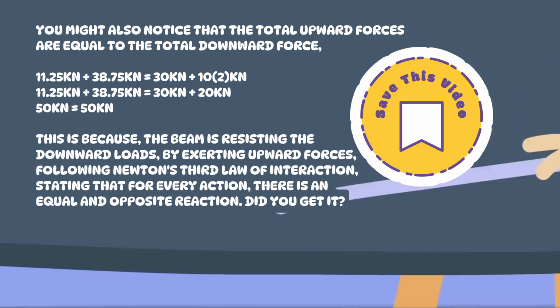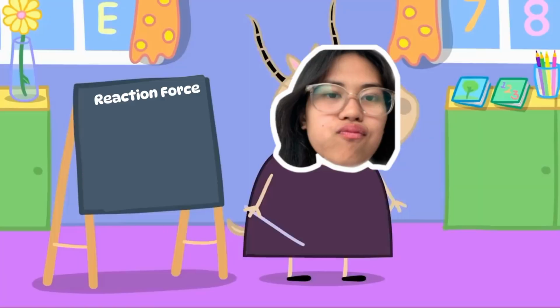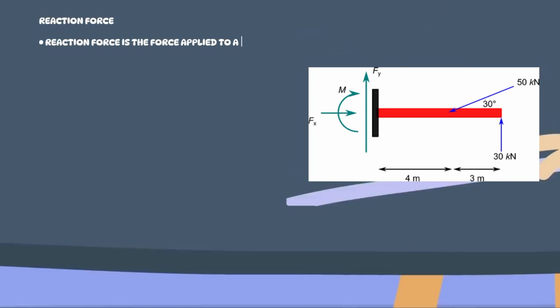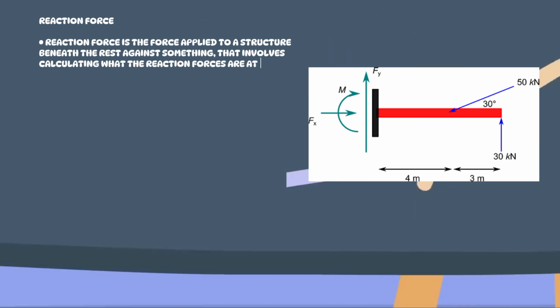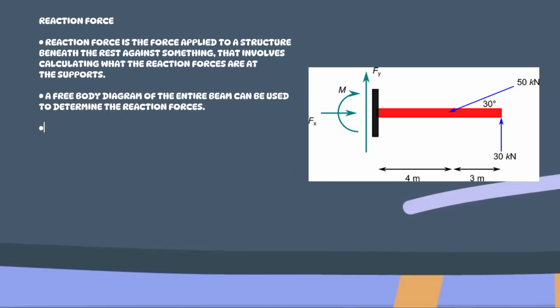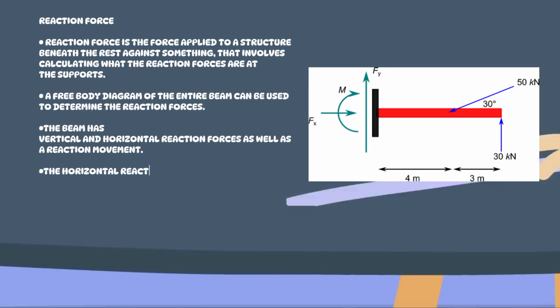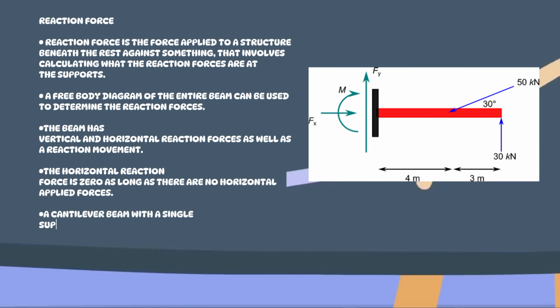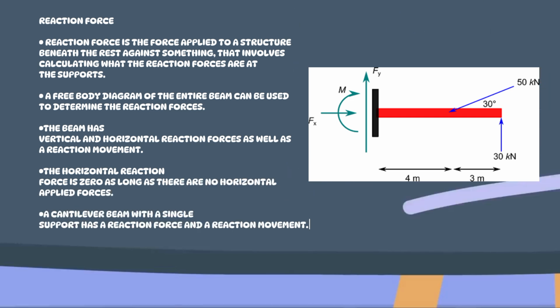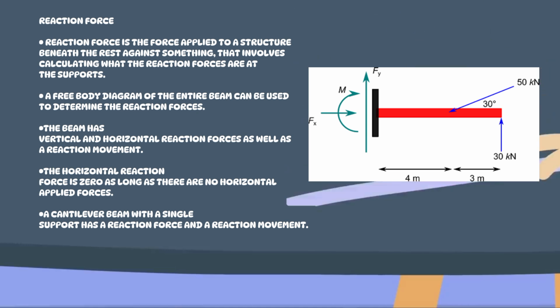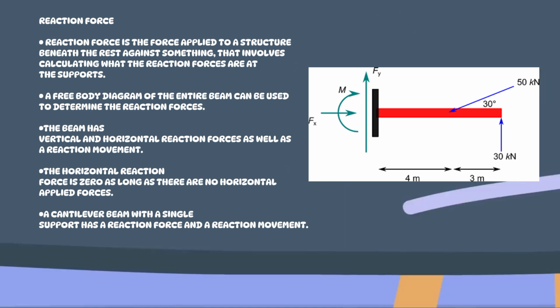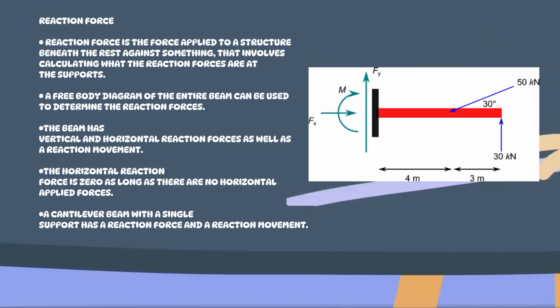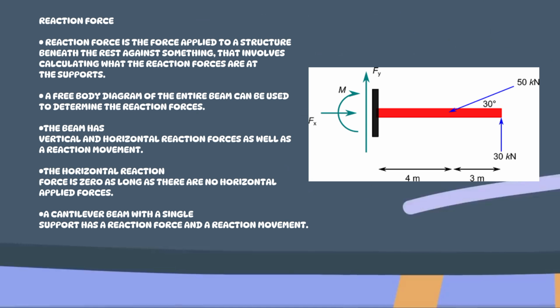Did you get it? Yes, reaction force is the force applied to a structure when it rests against something. In analyzing a beam structure, it involves calculating what the reaction forces are at the supports due to the forces acting on the beam. A free body diagram of the entire beam can be used to determine the reaction forces.